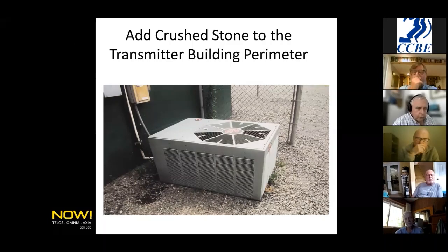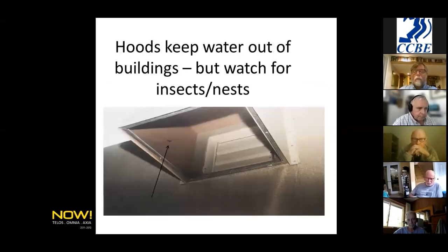You greatly reduce the propensity of them getting into your building by having gravel going out 6 to 8 feet all the way around. And they don't want to be out and be exposed, so they stay away. And this prevents them from getting close to the building and then finding an entrance way, whether it's a hole in the building or a hole in the door, or they try to chew through the wood to get into the door.